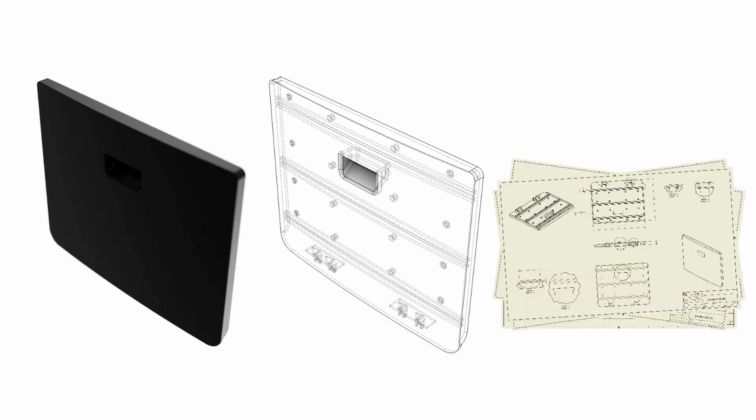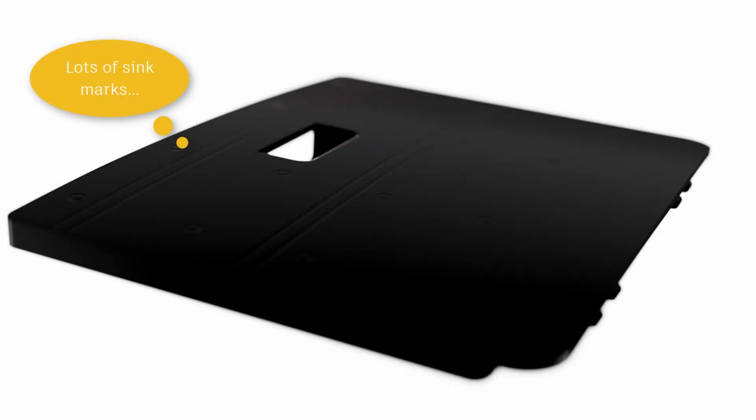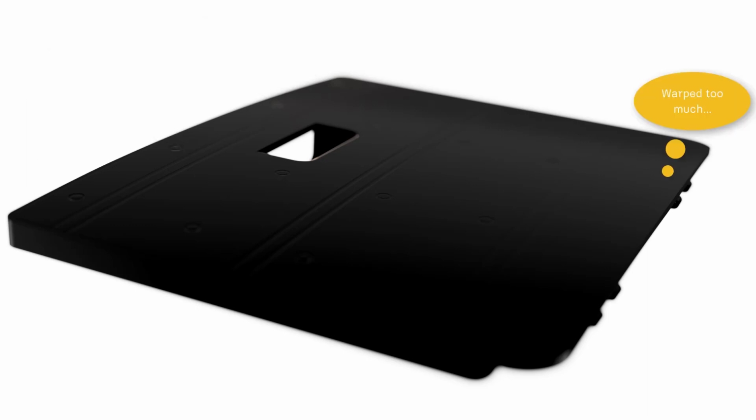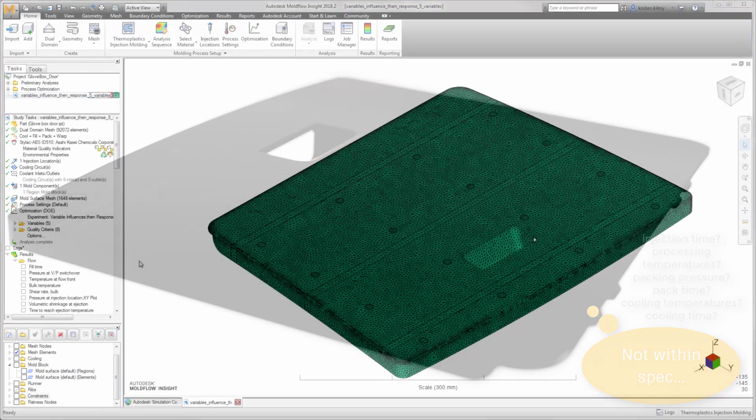Ideally, the manufacturing process to create a product would produce an identical match to the CAD model or engineering drawings. Realistically, however, this is not always the case. When working with injection molded plastic, a number of influences can cause minor or extreme variations, like deflection and part defects, within the manufactured part.